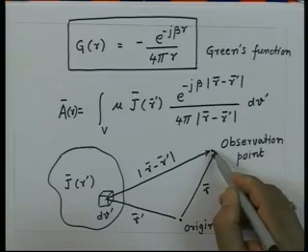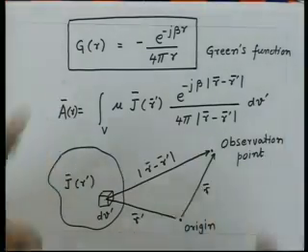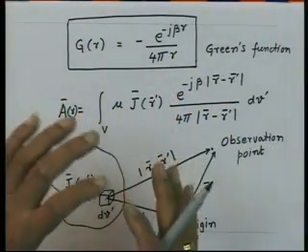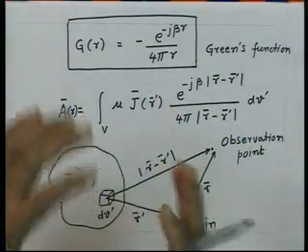Once we get the magnetic vector potential at this location, the problem is straightforward. Then we can go back to the definition of the magnetic vector potential, from which we can calculate the magnetic field or the magnetic flux density, and once we get the magnetic field, we can go to any of Maxwell's equations and solve for the electric field, and essentially we have the solution to the problem. Now we will take very specific cases and solve the problem, that means find the electric and magnetic fields for a given current distribution.